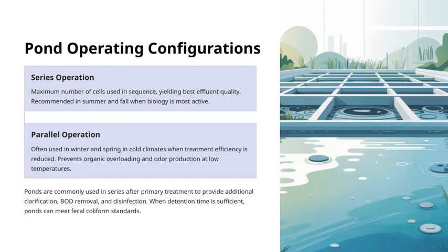It's also important to note that ponds are commonly installed in series after primary treatment. This configuration provides additional clarification, helps with BOD removal, and even assists with disinfection. When the detention time is sufficient, these ponds can meet fecal coliform standards, ensuring the water is safe and properly treated. Overall, choosing the right configuration depends on the season, climate, and specific treatment goals, and understanding these options helps us optimize pond performance throughout the year.